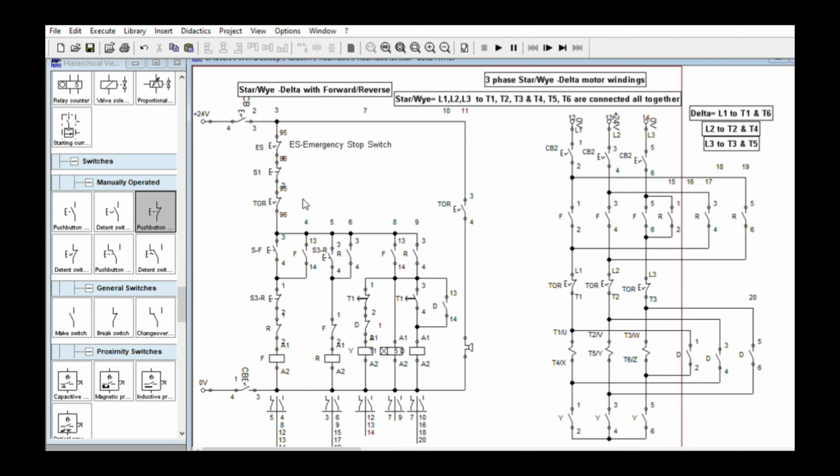No need to stop. The option here is two. You are going to stop or you are going to directly reverse the operation. But remember, you have to consider the load of the motor. Instant reversion will trigger high currents to the motor.